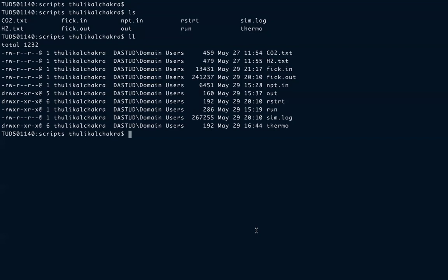To calculate Fick diffusivities, I have already mentioned that we begin by calculating the Maxwell-Stefan diffusion coefficients, which takes into account the cross correlations of the molecules of type A and B, where A here is hydrogen and B is carbon dioxide.